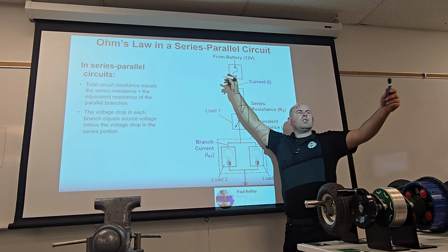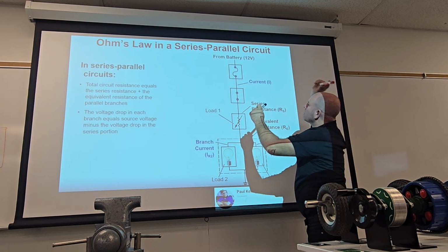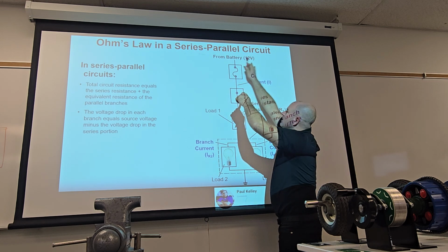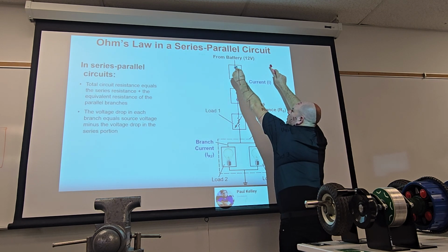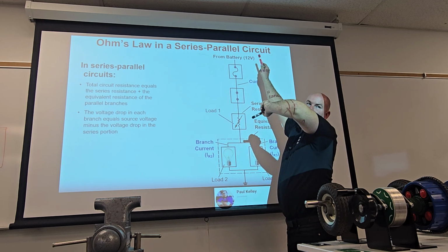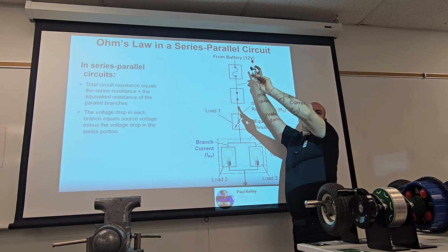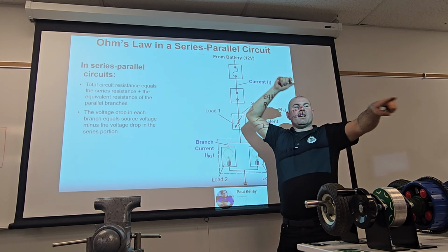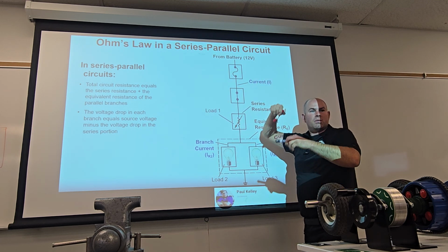No. So what I do is I put my meter lead here, and I put my other meter lead to the positive, and I put it on resistance. If I disconnected it, how much resistance should there be between positive and the fuse? Not 0, because I disconnected it. It should be an open. OL is correct. If I disconnected it, it should be OL.